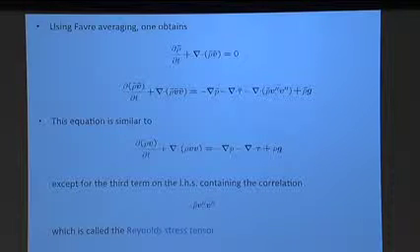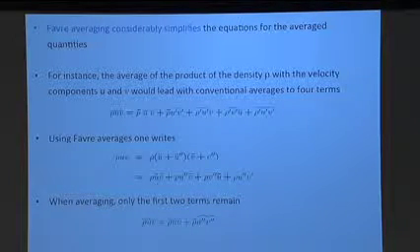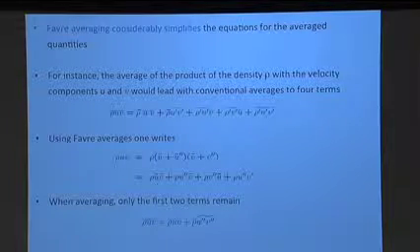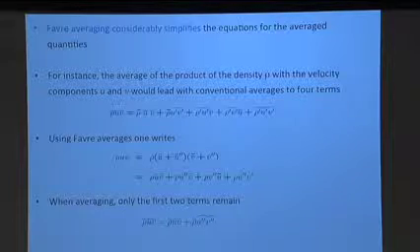It's just the same thing, just with the bars and tildes on top. Okay? However, if you have a nonlinear term, then that nonlinear term, and that was shown here, this is a nonlinear term, or here nonlinear term, that will always give you two terms. Because now, for linear terms, you always get a fluctuation mean, and that was 0 by definition. And for the nonlinear terms, you get a fluctuation times a fluctuation mean. And as long as these two quantities are correlated, it's not 0.